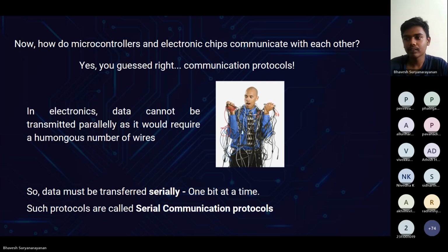7 to the power 13, I guess. Yeah, so it's just around 8,000 pixels. It has 8,000 pixels. So if you want to control each pixel independently, it means you will need 8,000 lines. You want to connect each pixel in parallel. It's not possible to do, right? It'd be so much work for such a small display.